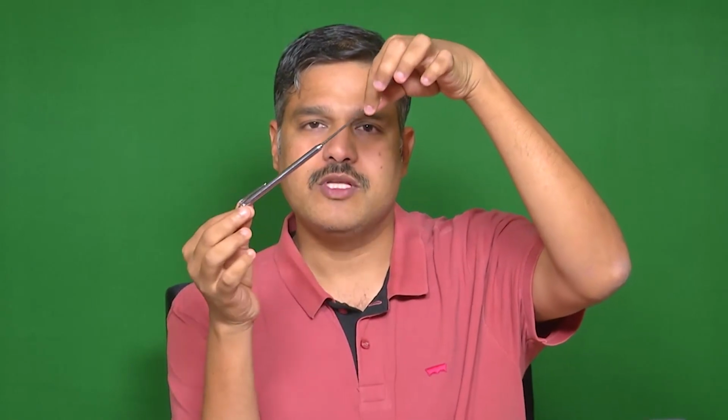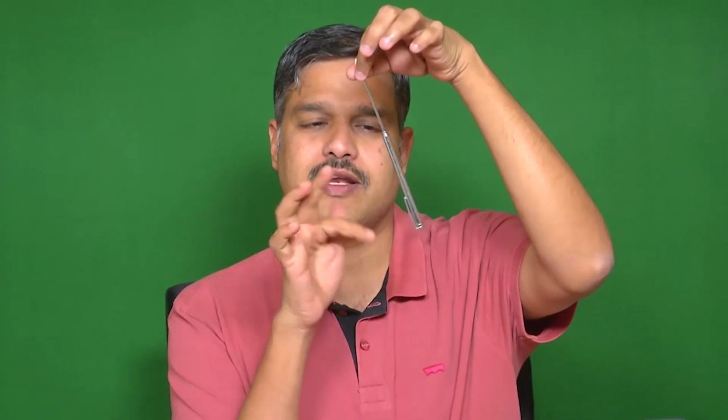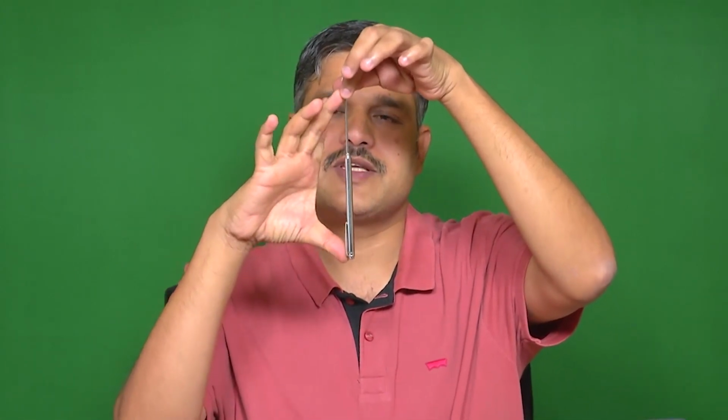In summary, what we have discussed in this module is degrees of freedom. First we discussed static indeterminacy, and second we discussed kinematic indeterminacy. So kinematic indeterminacy means the number of independent degrees of freedom which are required for defining the system. So for example, something like this pendulum is there, only theta is needed for writing the displacement of this pendulum. So L is fixed. If we have theta, we can say the x and y coordinates of the system at any point of time. So like that, this has a single degree of freedom system.